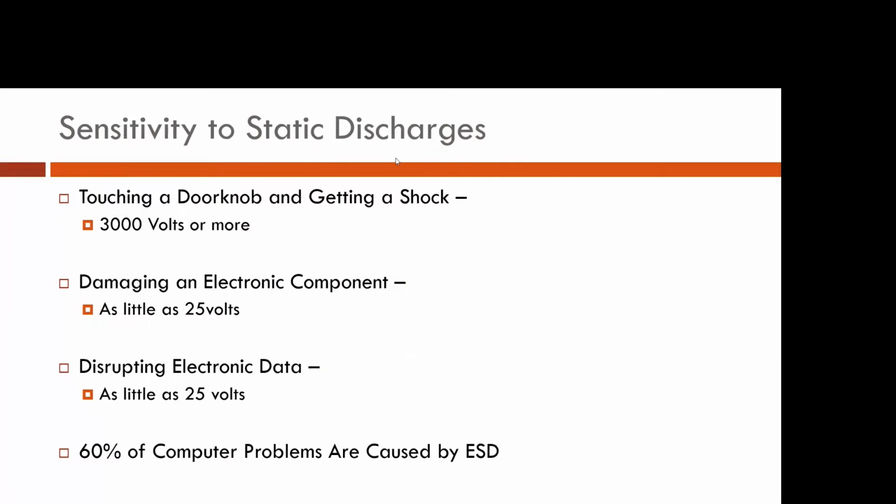Now, most computers, when they're sealed, that's called a closed box, generally can withstand about 7,000 volts of electricity. But when you're talking about the components that make up that computer before it's closed up, those are the sensitive parts. And generally when there's an ESD event and they get shocked, it's latent damage. So it's not present, it's not observable sometimes, and it gets built into the systems and then they fail or they don't live out to their life expectancy. So along the way, ESD has caused some kind of condition or issue where there's an ESD event and you can damage that type of equipment.